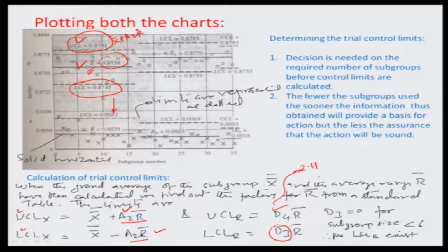But therefore, you can actually calculate the R bar and the UCL in this particular zone, and now all you need to do is to independently record the different x bar values. These open dots, for example, are those x bar values, and the moment it goes beyond control, you will see one value going out of this particular UCL or LCL. So, there is a very good real time indication of the process happening and how to control it.